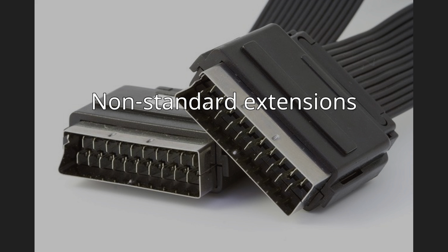Some DVD player manufacturers on some models offered S/PDIF only on Scart and an adapter in order to extract the digital audio signal to send it to a home cinema. To the present day, this connection remains rare, as HDMI, S/PDIF and Toslink can provide multi-channel audio. Also, some TV sets with built-in surround may have an optical or S/PDIF input beside the output.